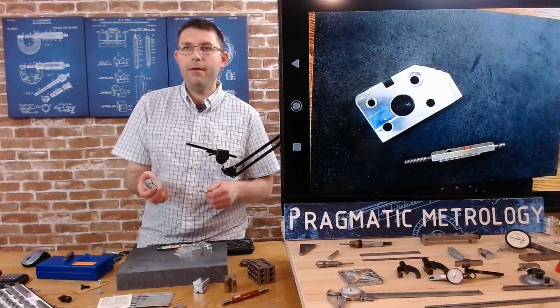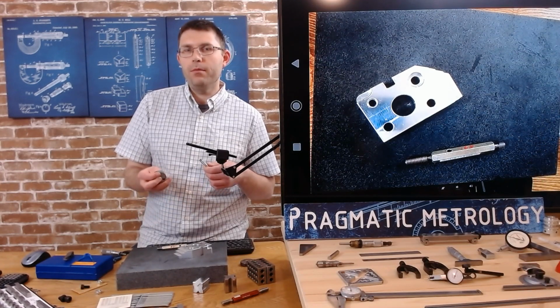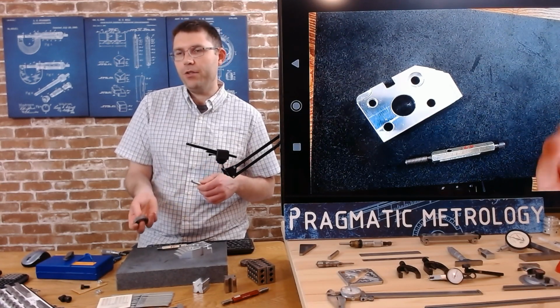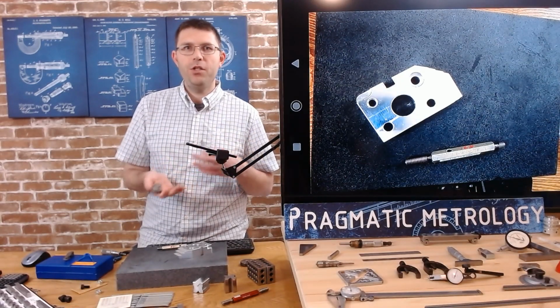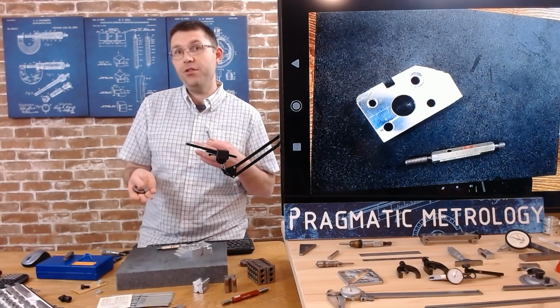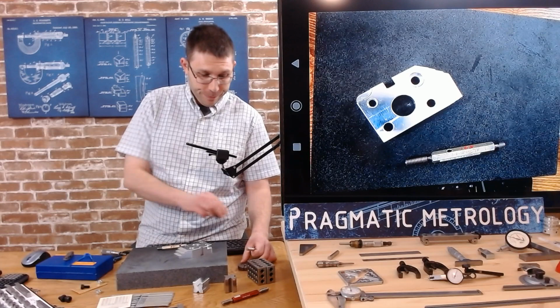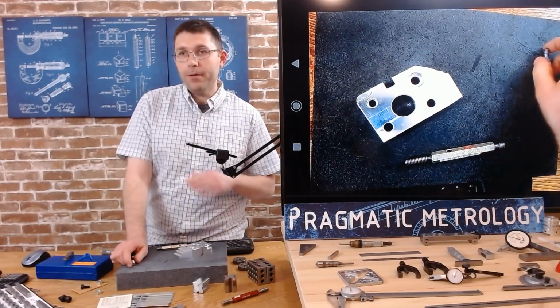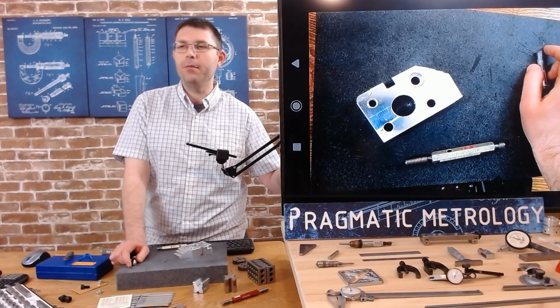Now if you have a 2A thread and a 3A gauge, or a 2A gauge and a 3A thread, that may or may not be interchangeable. The numbers when you're dealing with class 2 and class 3 change what's allowable for pitch diameter, so you can't always interchange them. But for the most part, they're still going to be very similar, very close, but there'll be minor differences.